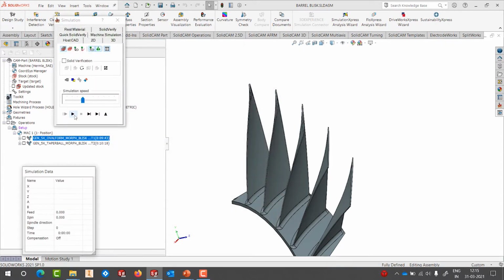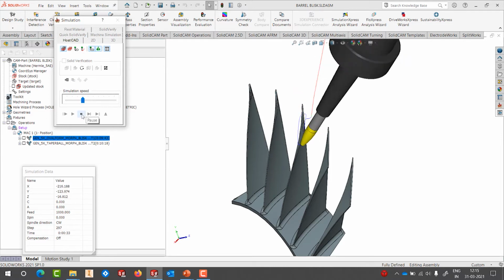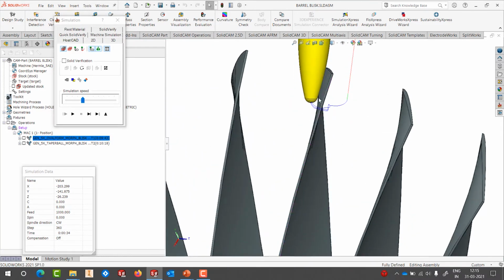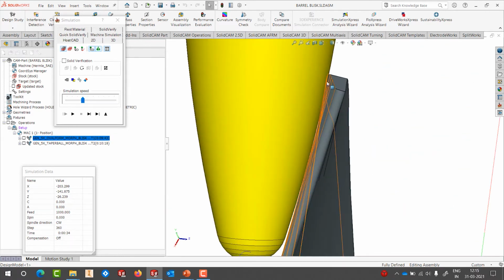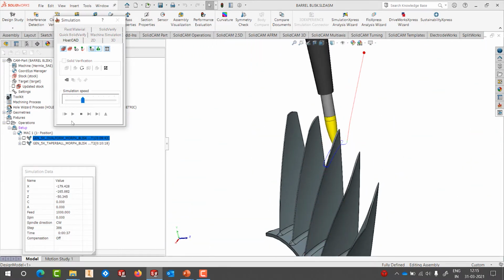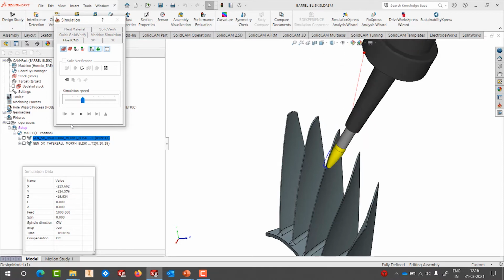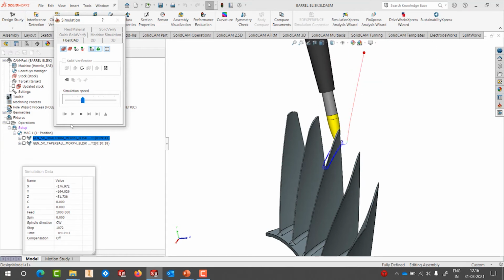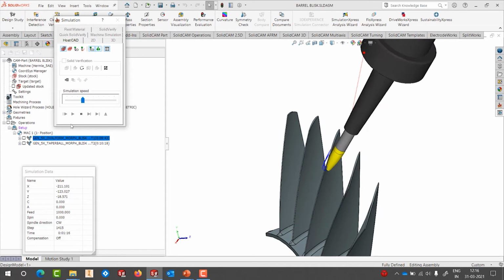And this is how my toolpath effectively looks. When it's cutting, it's actually using the barrel contact point. So if you look, my tip contact point is somewhere here, but my actual contact point of the barrel is up here somewhere. So that's the 40% margin or range that I've given. And this again can be achieved completely using the generic 5-axis. Everything is user defined, including the contact point, and you can have bigger step downs to generate the same kind of scallop that you would generate using a 0.3 or 0.2 millimeter step down using a bigger ball nose tool.